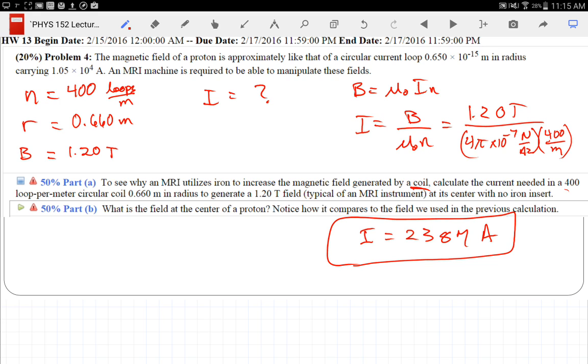Even with wires with really low resistance, that's going to be a huge amount of energy that is lost to I squared R, the power used by the resistors. Right, I squared R, you square that and you're into the millions. If the resistance is just like 1 ohm for the entire length, you still lose a couple million watts.